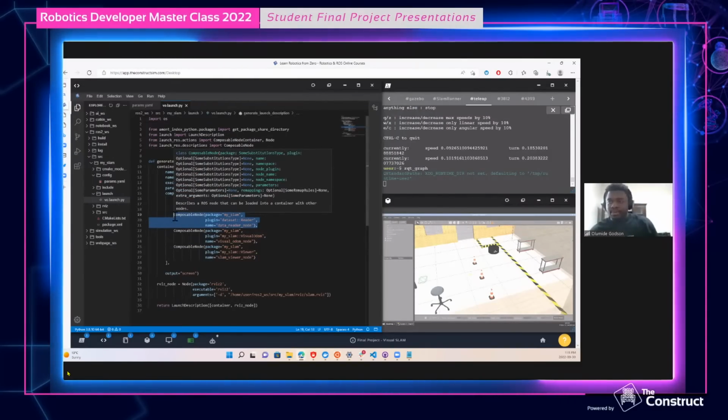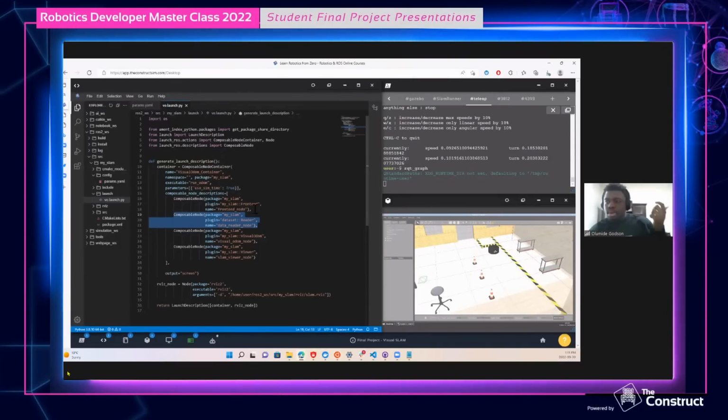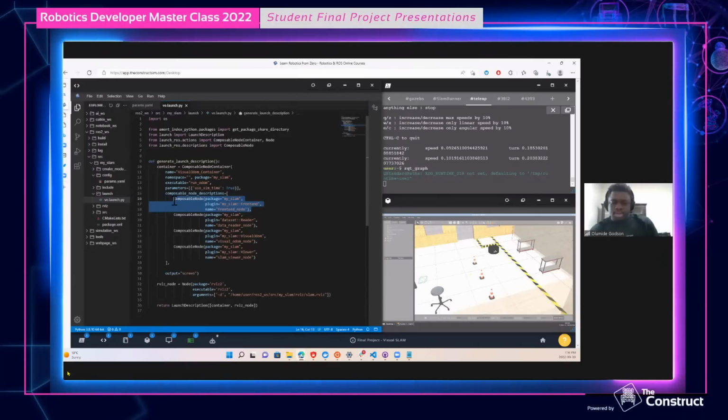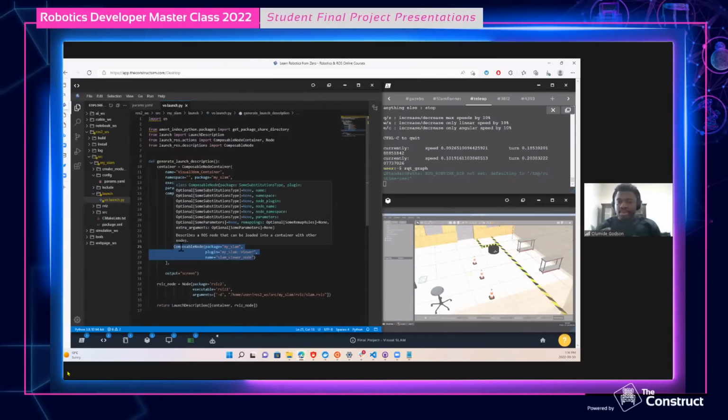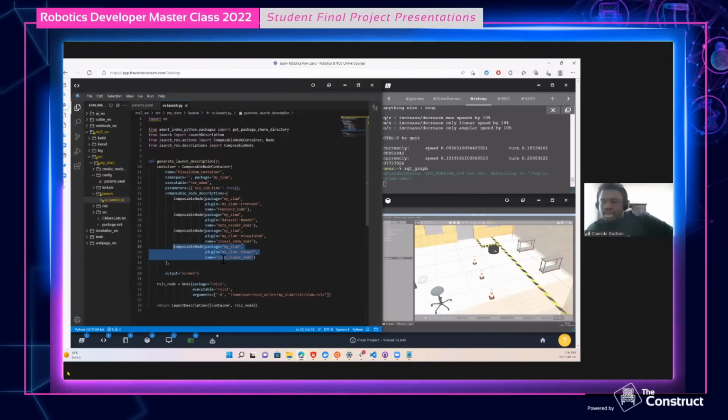It just reads the sensor information from the camera. Then there's the front end node that does the initial pose estimation. The backend was not implemented as a node because it doesn't directly use anything ROS related, so it's just a single thread that runs by itself. And then there's the viewer node for publishing topics, such as the images we saw previously that showed the detected images and the transition images. That was going to link to the web page so you'd see it that way, but I couldn't get to that, unfortunately.